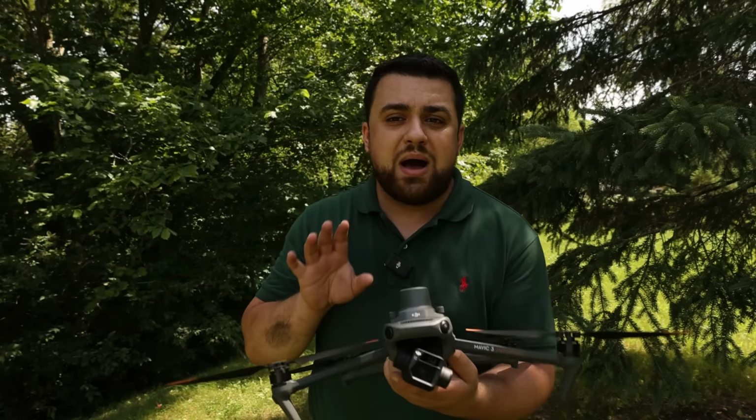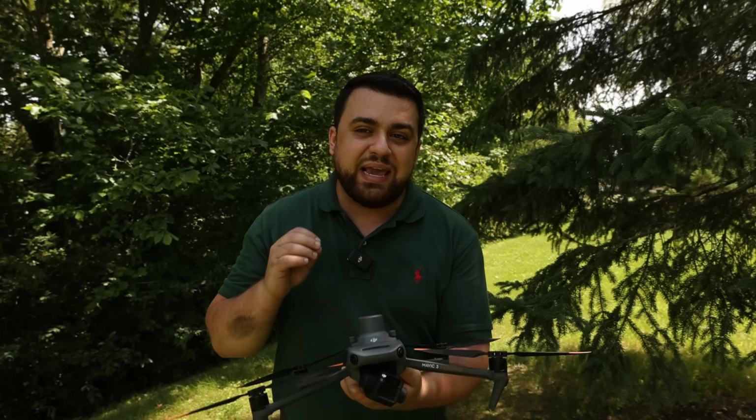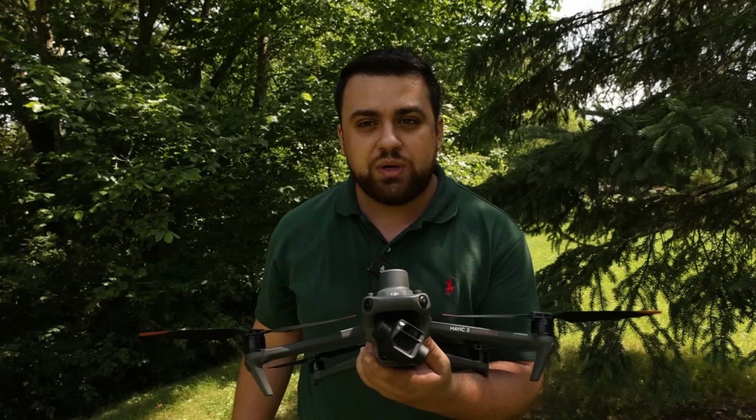Now, let's talk about the science of photogrammetry and how it has become a game changer in the surveying industry. Now, photogrammetry utilizes imagery in order to create a 3D model by utilizing the focal point of several images and reconstructing the scene in which we are collecting data. That means while our drone is flying in the air and just taking pictures for us, it's important that we have a clear and visible image every single time so that the photogrammetry software that we process all of our images into can generate an accurate 3D model.